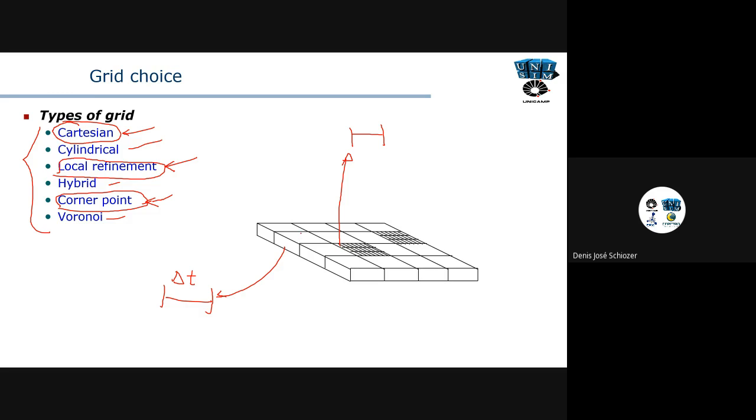For example, if I'm solving for this size of the blocks here, I can use a time step of, for example, 30 days. But for this one, as the block is too small and pressure and saturations are changing too much, sometimes I have to use a smaller time step, for example, here, 5 days.